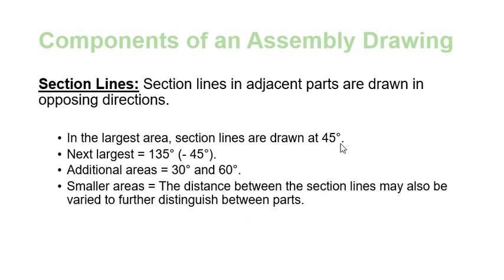Most of the time we just use 45 degree section lines, because in this textbook you're not dealing with a very, very big area anyway. So most of the parts in the system in this textbook, you can usually go with 45, and we don't ever have to use bigger angles. So what it's talking about depends on the size of the area you're going to deal with, the different angles of the section lines, and also small areas, of course, reduce your line angles.